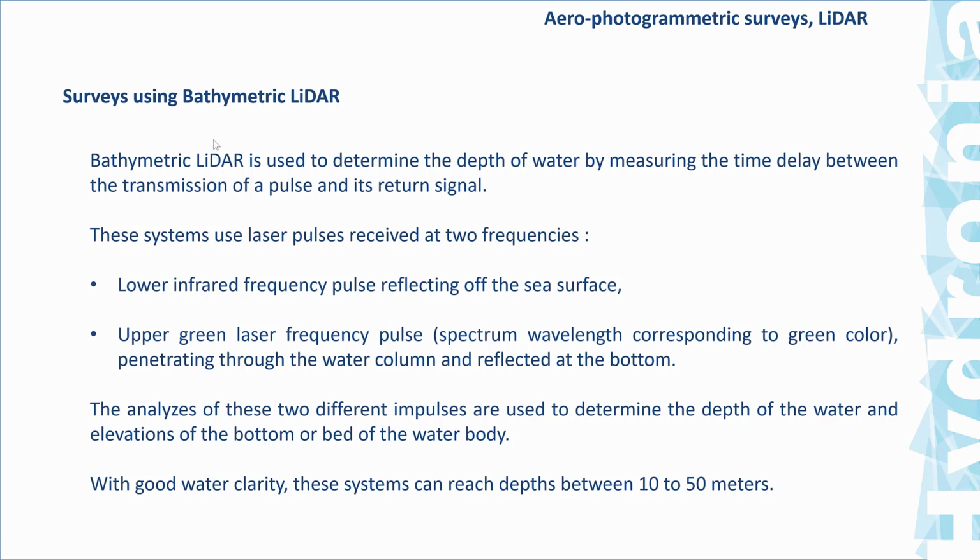Now, there is a big limitation of the LiDAR, that is that they normally are used to obtain the terrain surface, but when they go over a river, they just get the water surface. And that's the standard LiDAR. When you have a standard LiDAR and it goes over a river, it will obtain only the water surface and not the bed or bottom elevation of the river.